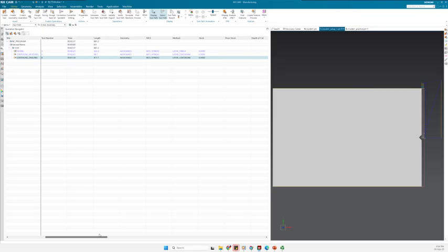So then we can see that the drilling itself took 1 minute and 34 seconds, including 1 second that I was defining for the dual time. And then you can have the other values, feed rate, speed and rate. I put the value on the spindle speed, but I didn't put anything on the feed rate. So these are now random values that are here. And you can see the status of other parts itself.